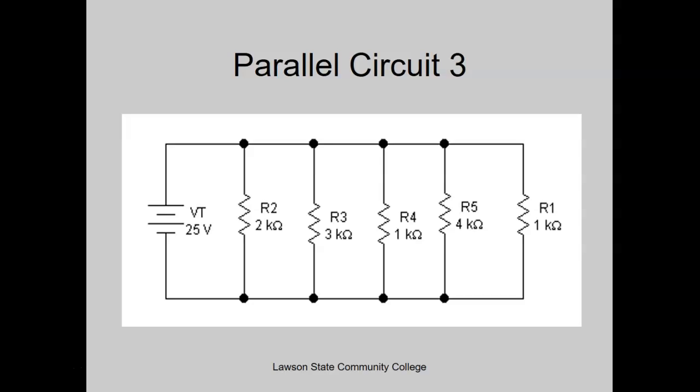You're not adding your resistance. You're adding the conductances. So you have to get each conductance, then add it all together, and that will get you 3.083. But why total 324? Because once you find your total conductance, then you inverse it to get your total resistance. And now if you do 3.083 inverse.